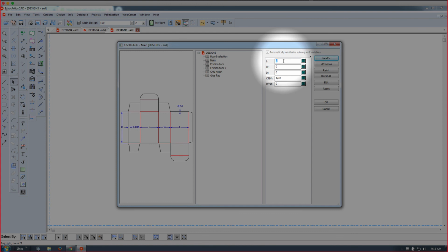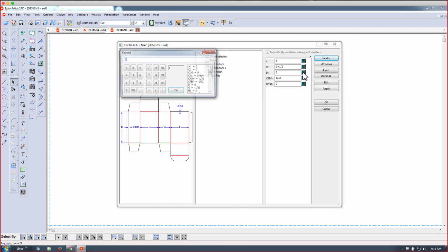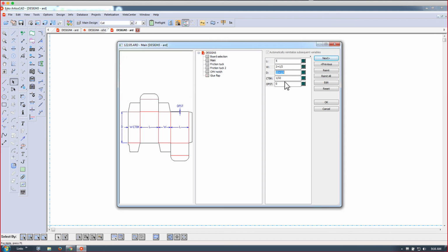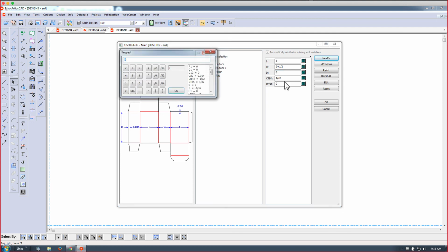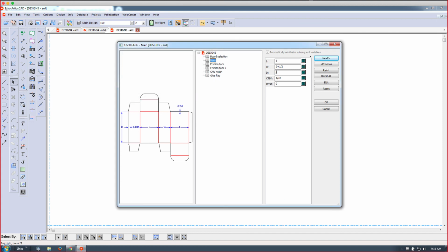parametric design here allows me to enter my dimensions: length, width, and depth. If you also want to use fractions, you can use this green icon representing a calculator, where you can pick from predefined standards. So if I wanted to do 8 1/4, I can do that like so. 8, space, followed by a space and 1/4. There you go, 8 plus 1/4.